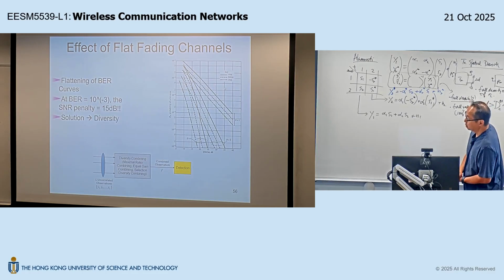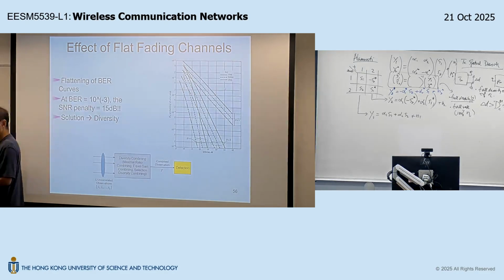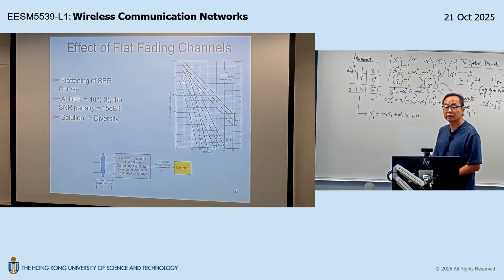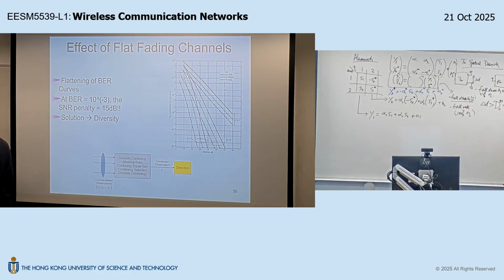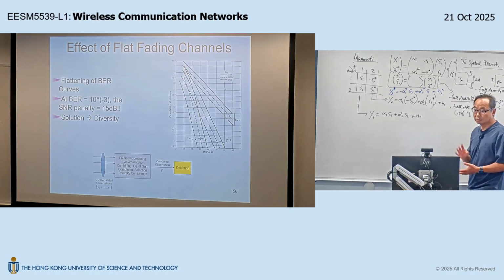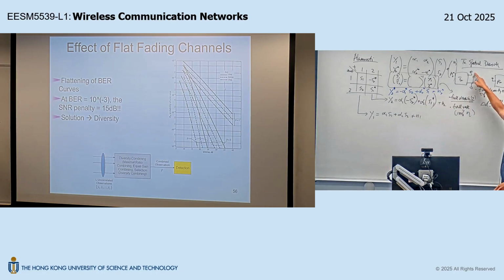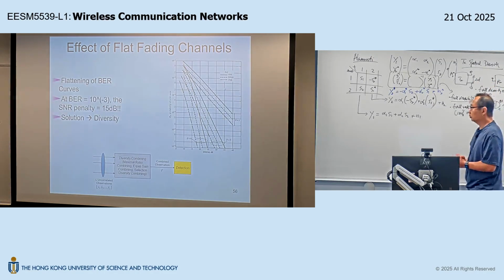All right, so these are the different ways of creating diversity observations. You have transmit spatial diversity and receive spatial diversity, involving multiple antennas. And you can mix these two together, obviously. You can have multiple antennas on the transmitter and receiver as well. In this way, for example, if you have 2 transmit antennas and 2 receive antennas, the full diversity order would be 4, because if you think about all the possible alpha, you have 4 independent alpha. So the maximum diversity order would be 4.